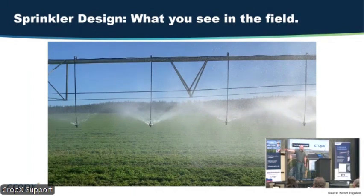So if you're ever out in the field and you don't see a nice steady stagger from low flow to high flow at the end, you have an issue out in the field, okay? Or we're not putting the right amount of water in the right spot. Those are things that even if you're not in the irrigation industry or the mechanized irrigation industry, you guys can point out real quick for growers, right? They will see this in the yield monitor at the end of the year, right? If this isn't the right way.